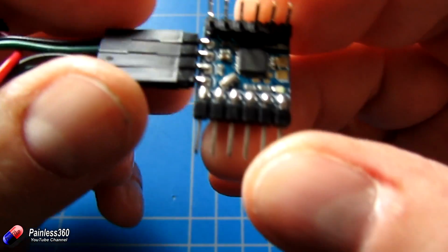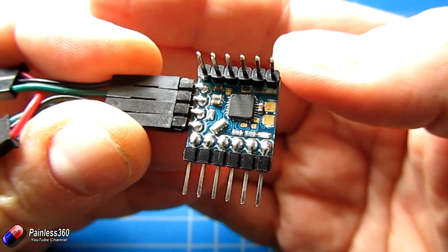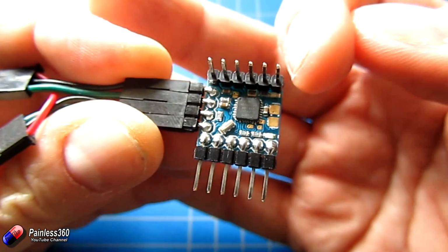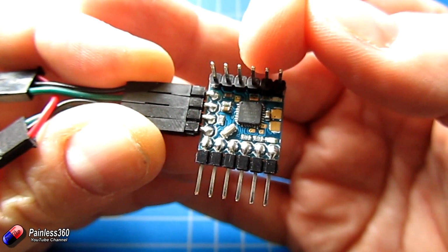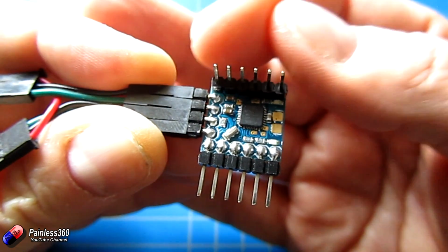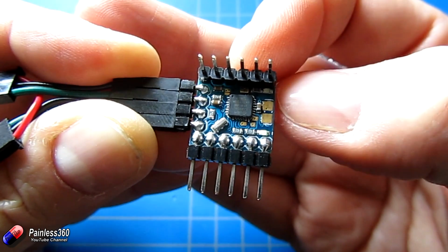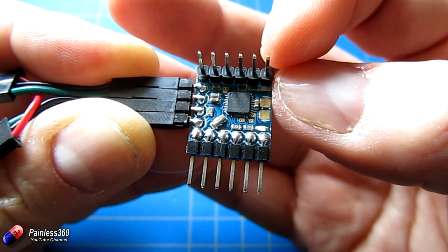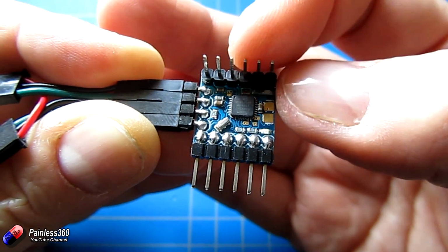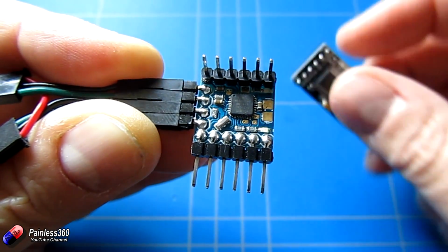Now the other thing we need to check is on this board, the way it works is these top pins go ground, ground, 5 volts, then you have the 2 signal pins and then ground. So looking at the top like this, where we have our ground and plus 5 volts on this side, it's ground, ground and plus 5 volts. Plus 5 volts is that 5 in that middle pin.